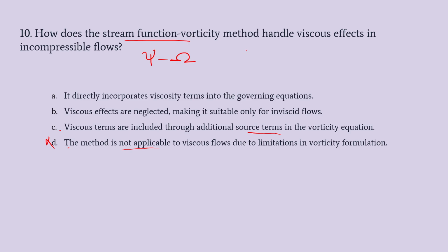That is, considering a two-dimensional flow field, our u velocity and v velocity, that is velocity in x direction and y direction, are converted into psi, the stream function, and vorticity through the existing relation between stream function and our velocity components, and the equations are solved for stream function and vorticity.